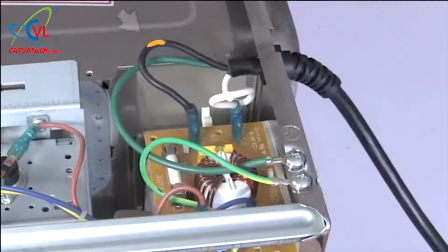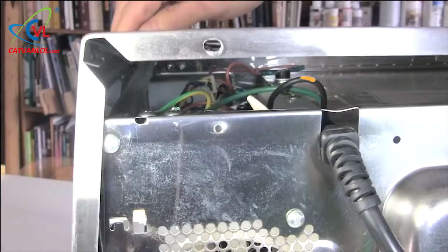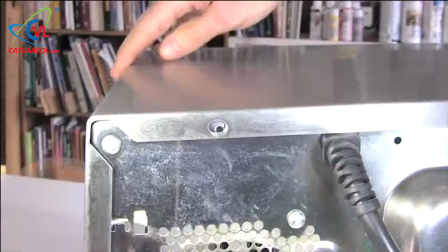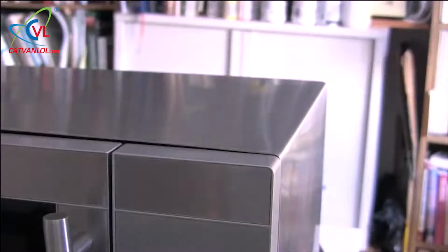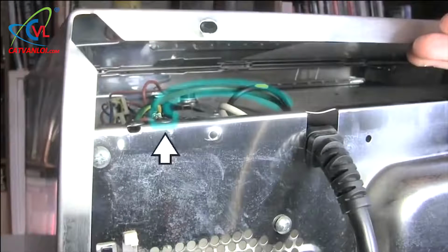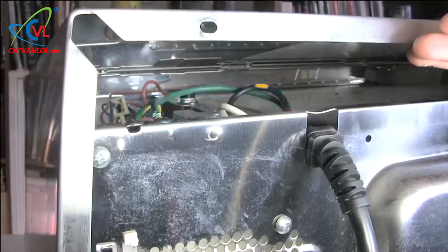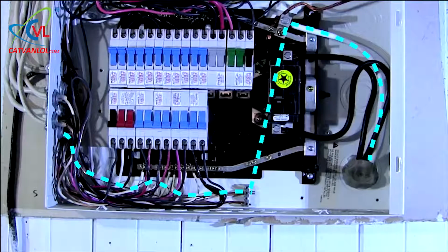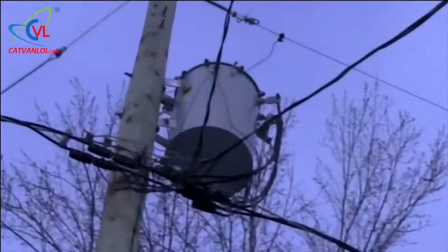But what if the insulation around the hot wire gets damaged, and the wire itself touches the metal case? The case is now connected to the hot wire. If you were to touch the case, you'd get a dangerous shock. But luckily the ground wire is connected to the case. That ground wire is a very low resistance path for the electricity, and so it will flow from the hot, through the case, through the ground wire, and back to the panel where the ground is connected to the neutral, and back to the transformer, completing the circuit with the hot wire there.